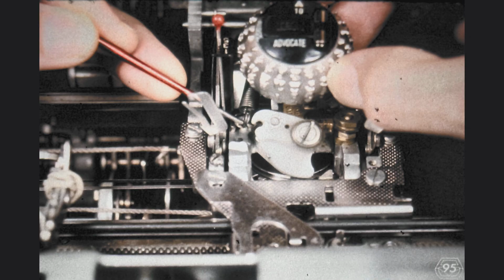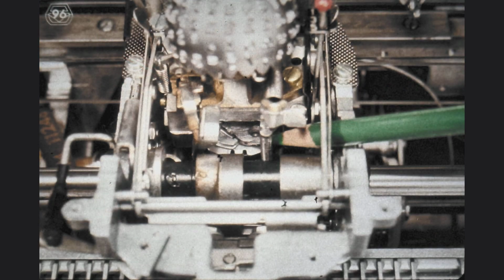However, before we start with adjustments, we will first practice removing and reinstalling the rotate tape. The rotate tape breaks far more often than the tilt tape, and it is very important that we become proficient at replacing rotate tapes. This time, when removing the rotate spring tension from the rotate tape, we will go a lot further. We start by closely watching the rotate pulley while we turn the element counterclockwise.